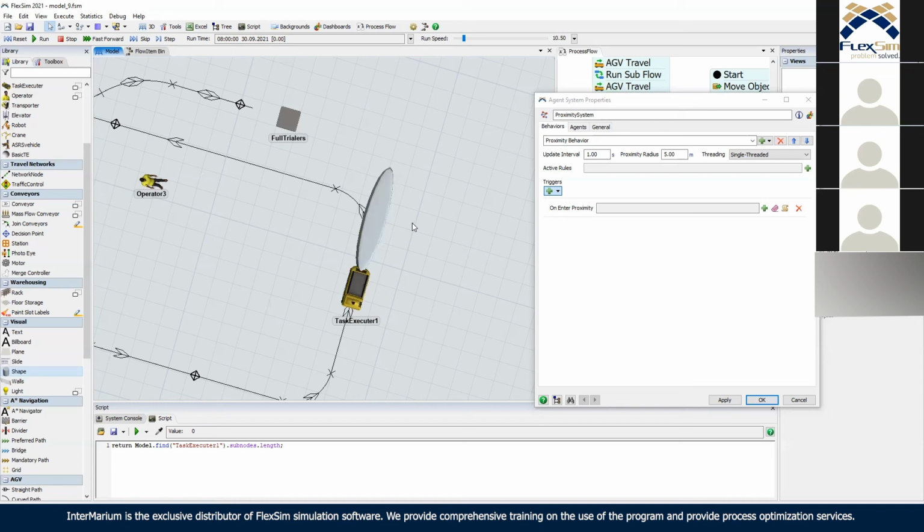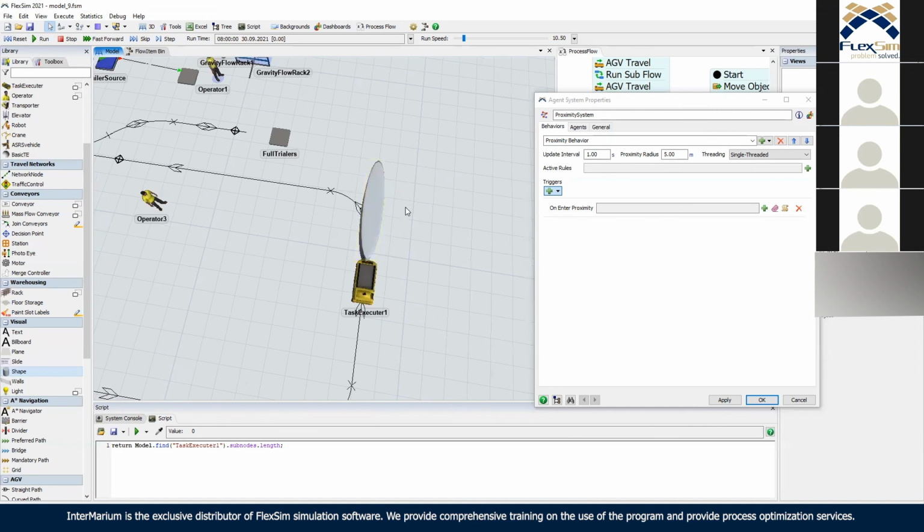For AGV, my way of doing things would be to program this triangle, because this is more realistic here, because not a lot of AGVs see what is behind them, and the operator can freely go just behind the AGV, and the AGV won't see it. It can be used. It needs to be a little bit tailored, and the question is always the same: what is my goal here? Do you want to model this collision, or do you want to see what is the impact of possible collisions in my AGV, depending on the number of operators on the line?